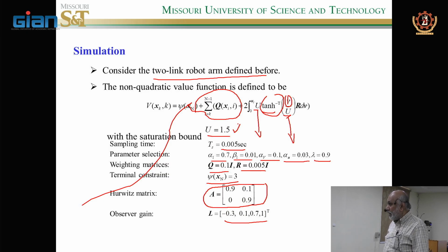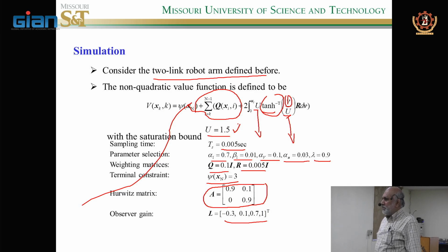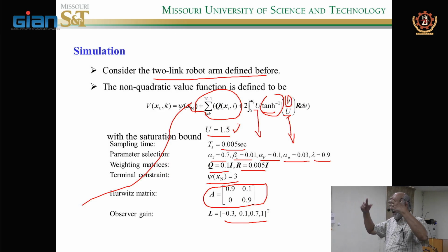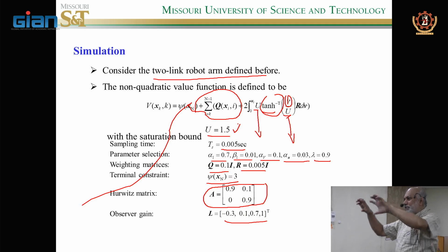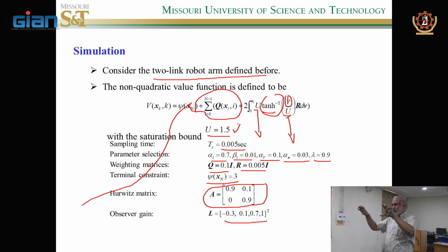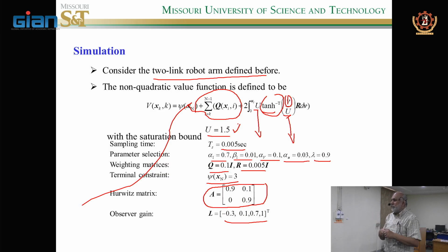I would not use inversion. I know in aerospace that's very common, but inversion is always a problem, for many reasons. One is, if the inversion is not exact, then you don't get an identity. The idea is you have the nonlinearity and you try to invert it, so that phi inverse phi is identity and the system becomes linear. But suppose there is some perturbation, then these two don't match exactly. That's the problem, but even what I presented here, actuator saturation still holds good.